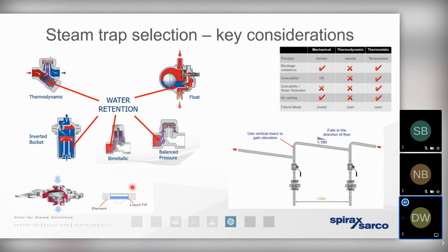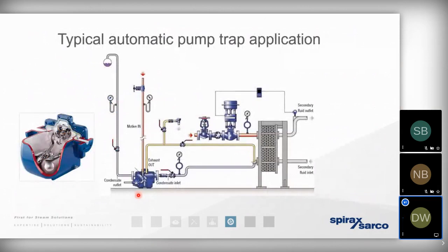It's got a little element contained within it, and that element should be maintained periodically. Better still, it should be totally replaced somewhere between every 3 and 4 years, depending on the process, and that should be written into the scheme of inspection just to guarantee that we're not further reintroducing the risk of contaminated condensate. And on the topic of condensate, as we've mentioned, we need to ensure that the condensate is being drained away from the process adequately. And that's where the automated pump trap really has got its place.